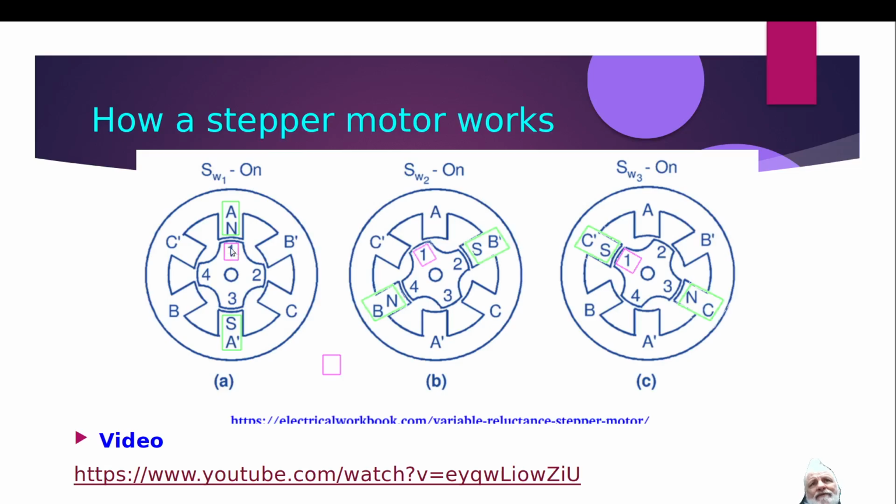Again, we have a permanent magnet on the rotor part that's going to rotate, and then we have these coils, and the idea is we can control the speed and direction by putting pulses on these various different coils, and we can get this thing to rotate.